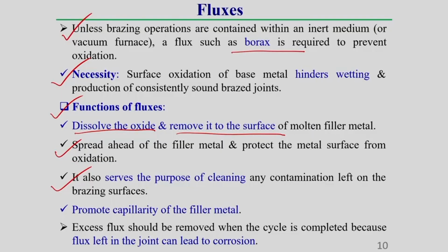It also serves the purpose of cleaning any contamination left on the brazing surface. It helps to promote the capillarity of the filler material. This is a very important point, that flux also increases the ability to wet, as well as promotes the capillary action.